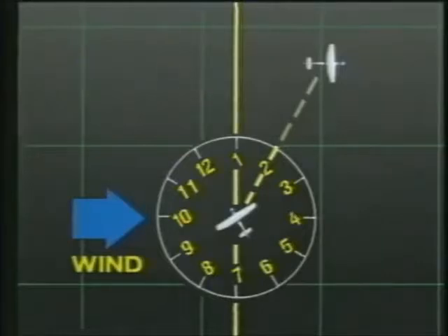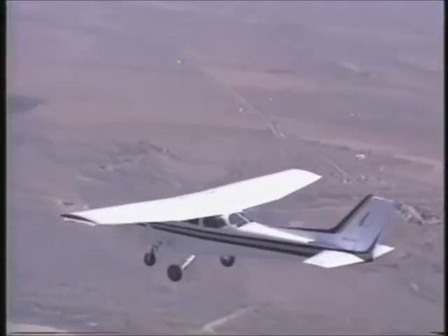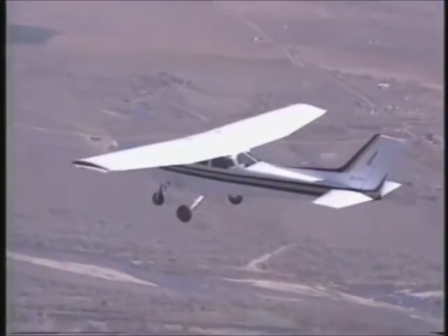When you're trying to locate the reported traffic, consider your ground track and encompass a wider range in your scan. Let the controller know whether or not you have spotted the traffic. If you don't see the traffic, tell the controller negative contact and continue to look. Keep in mind that traffic advisories do not relieve you of the responsibility of maintaining your normal scan for collision avoidance.